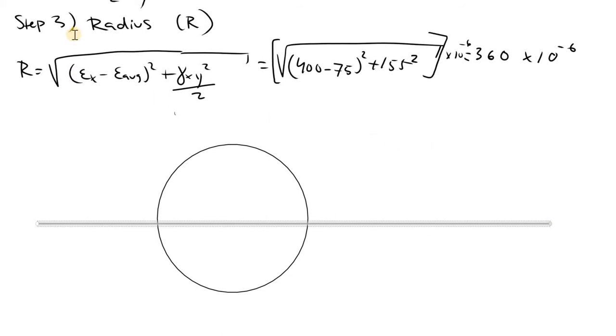The horizontal cuts half through the circle. Ideally somewhat correct. There we go. The positive axis is to my right hand side for the normal strain. My shear strain will still remain on the vertical axis, but first let's locate our center point in here. This is my center, C.